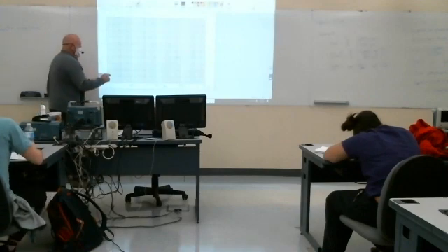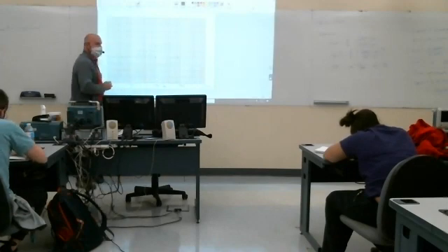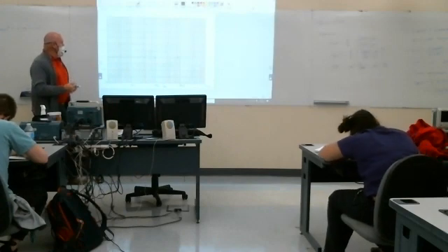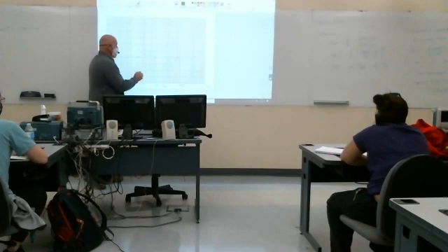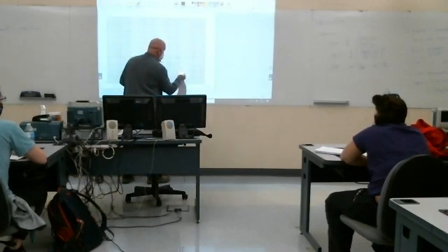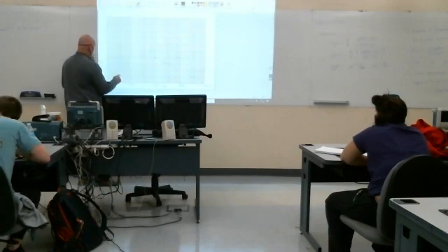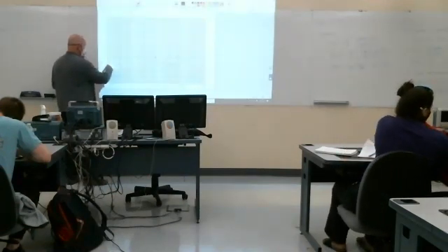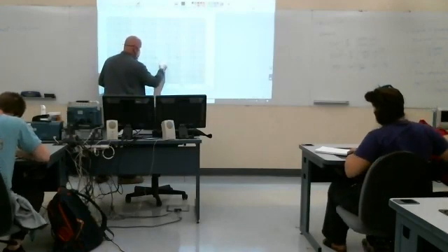So what does the pole term do? Okay, it's that. And then here's where it's helpful to have a ruler when you're doing these things. And then now this goes down at a 20 dB per decade rate. Okay, it goes down because it's a pole term. It's in the denominator. So it would go like that. Okay, 20 dB per decade. If you'll notice, well, let's see, 6 dB, so this is 10, this would be 8, this would be 6, so 6 dB is right there.